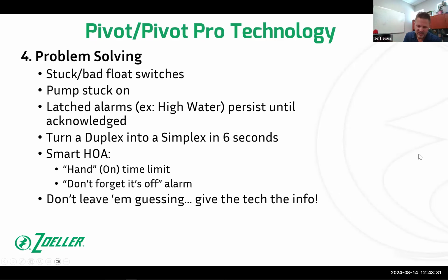And then the other thing is that continuous run alarm. You want to make sure you're thinking about what the cycle time of this pump is in this application. Is 20 minutes appropriate? Maybe it isn't most of the time, and you have to change it.